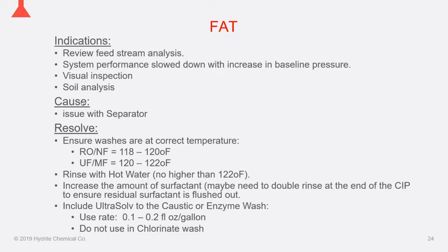And finally, that can sort of be incompatible with chlorine usage, which can raise some concerns about whether or not taking out the chlorine is going to lead to more fouling. But if we're strictly dealing with fat, chlorine is not going to do much to remove that fat. So in a remedial wash, we want to go ahead and have more washes that are targeted with surfactants and the Ultrasolve, and we can see a significant increase in the cleaning of those membranes. And if it is a fat issue, they're going to be returned to capacity pretty quickly.